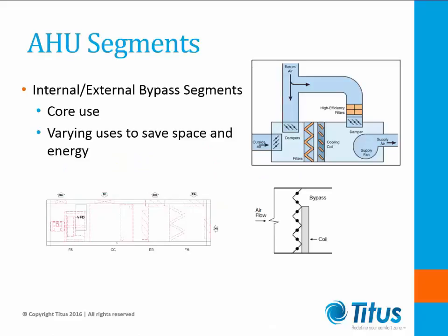Let's reference the underfloor application for a moment. For occupant comfort, discharge air temperatures are generally in the range of 61 to 65 degrees Fahrenheit. These are warmer than overhead leaving air temperatures, which range between 50 and 55 degrees Fahrenheit. Dehumidification is a necessary process to maintain occupant comfort. If you look at the psychrometric chart, you will notice that the 61 to 65 degree range will result in an unacceptably high relative humidity in the occupied space.